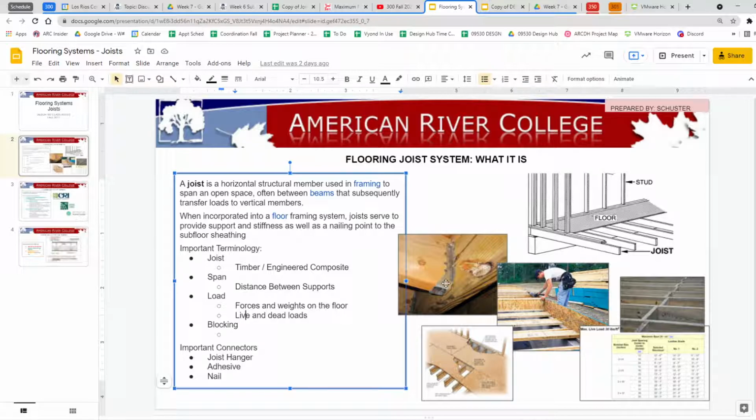Okay, and that's a very strong, very standardized way. In other words, you know how much load that joist hanger will hold. They've designed them, they've engineered them, they've tested them. If you use a certain size nail or screw on the pattern that they give you, and you put them in the right order, and you drop this in there and tap it in, this will hold a certain load. And they can tell you reliably that that joint will hold a certain load.